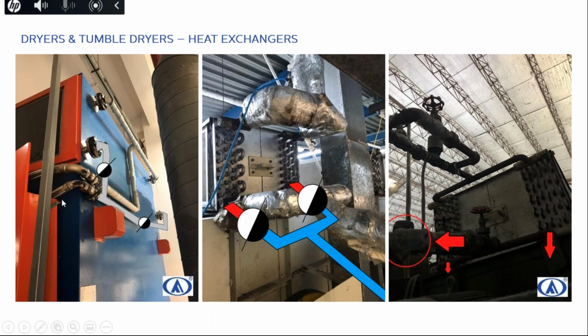If it's with 1 steam trap, there may be condensation for one of them, and fully steam for the other, and if this steam reaches the steam trap, this condensation will cause damage and heat drops, heat loss, energy drops in this steam heat exchanger. To prevent this, you need to use 2 steam traps, which are float type.